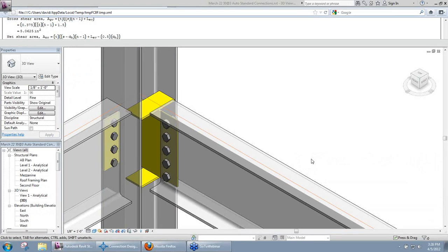So another question that has come up here is someone is asking, if I make a change in any of the shear plate settings, do I have to make the same changes and setup in SDS2 as well? So sounds like you're, in this case, concerned with transferring models from Revit into SDS2, probably concerned with if settings are being changed here that they match in SDS2.